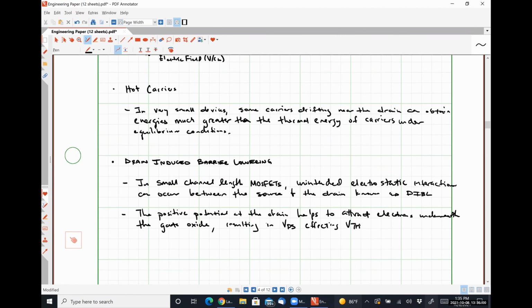For a C5 process, which is what we're designing things around, the minimum acceptable channel length is 2 lambda. It's practically always going to be 2 lambda, but for a 300 nanometer process, that means we're looking at 0.6 microns. So pretty small, but not wildly too small. And we can put voltages of up to 5 volts and not see anything like this occur.